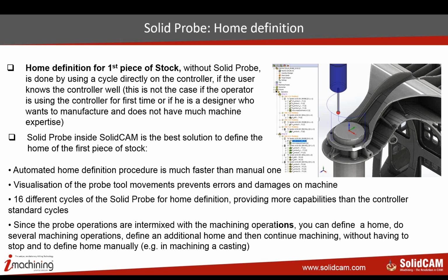But even in this case, when you define the home only for the first part, it's safer and faster to do it with SolidProbe, because you see what you program, you see the simulation, and you eliminate any chance of collisions in the machine.